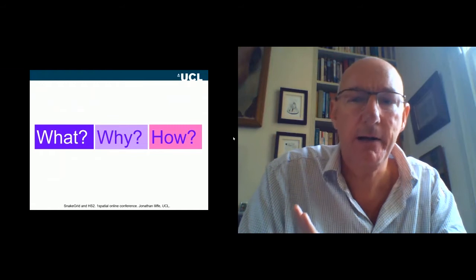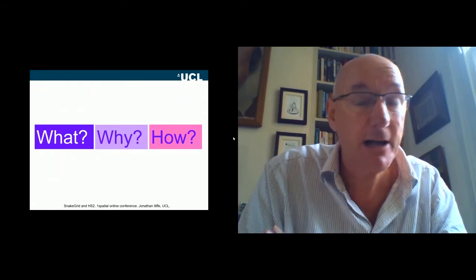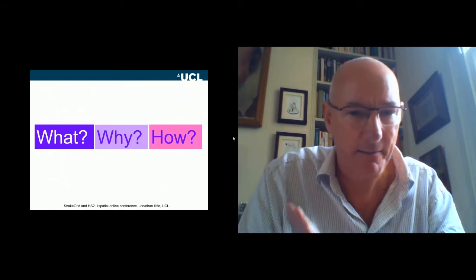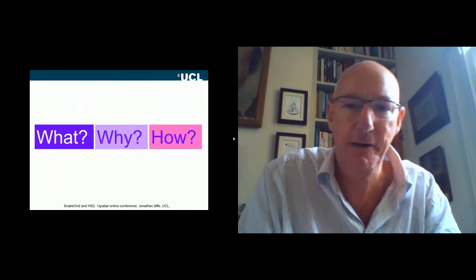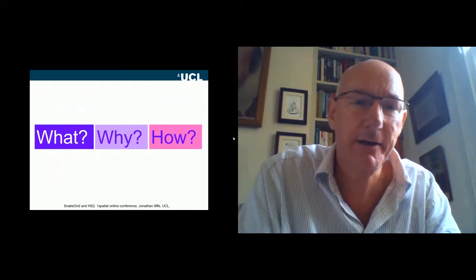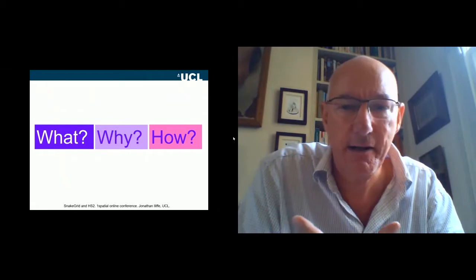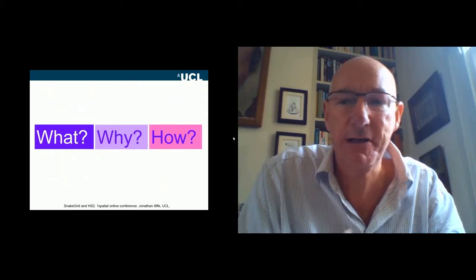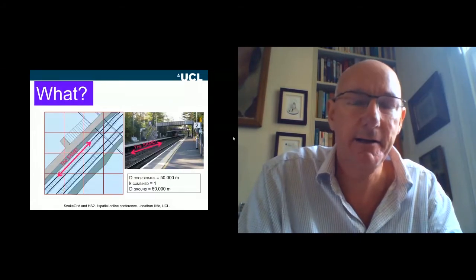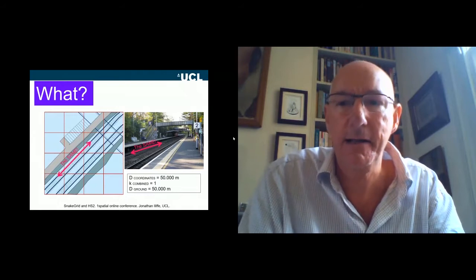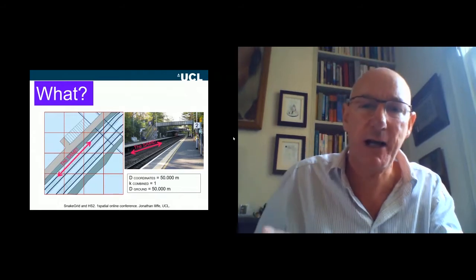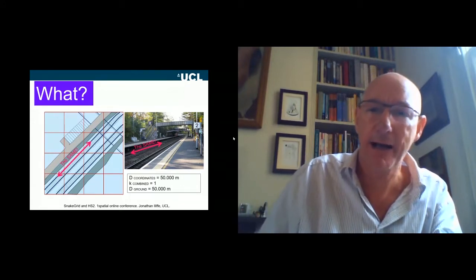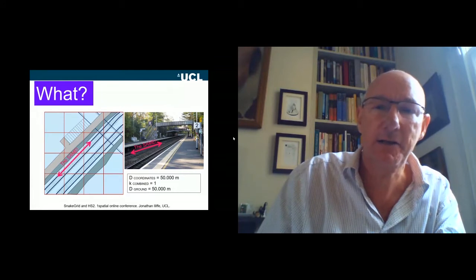SnakeGrid is purely about trying to introduce a coordinate system that matches reality. It essentially says that something which you measure off a map, in its crudest form, is the same as what is on the ground. In a more precise concept, a radius of curvature which is designed to be of a certain length in a design system gets created at the same length on the ground. It doesn't suddenly change when you go between the coordinate system and the reality. Fundamentally, that's what HS2 wants to do.